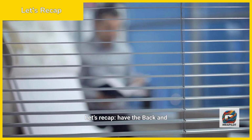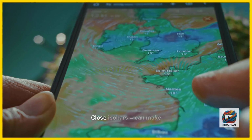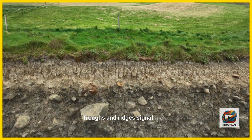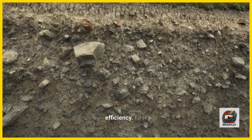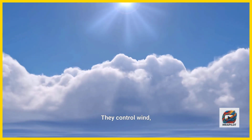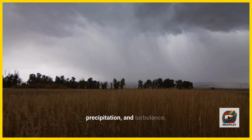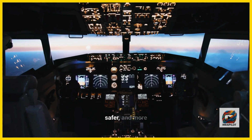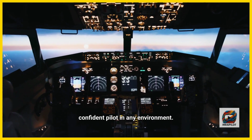Let's recap. High pressure equals sinking air, clear skies, clockwise flow. Low pressure equals rising air, clouds, and rain, counterclockwise flow. Close isobars equals strong winds. Troughs and ridges signal changes ahead. Pressure systems are the engine behind most weather. They control wind, cloud formation, precipitation, and turbulence. Mastering this topic helps you become a smarter, safer, and more confident pilot in any environment.